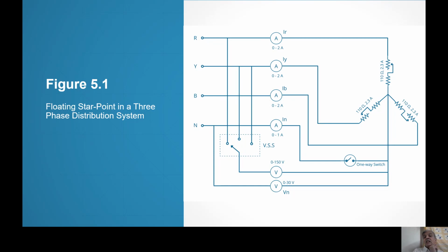And if we want to avoid the bad effect of that unbalance, we have to connect the neutral of the system, the neutral of the distribution transformer, physically with the neutral of the load. Neutral should go continuously, physically, everywhere, in every house, in every industry. It has to be run, right? You might have seen on distribution poles also that there are 4 wires, R, Y, B and neutral. 4 wires are there.